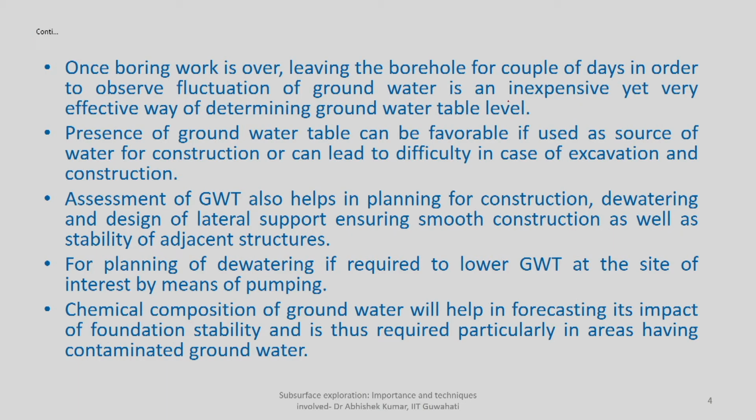So, you can leave that borehole, but you have to make sure you make safety measures properly there, and then observe the groundwater table level maybe after a couple of days or maybe after a couple of hours, because now you have the soil type available at different depths. That will indicate whether you have to wait for a couple of days or a couple of hours for determination of groundwater table. And since you are not drilling a borehole separately, this will be significantly inexpensive.